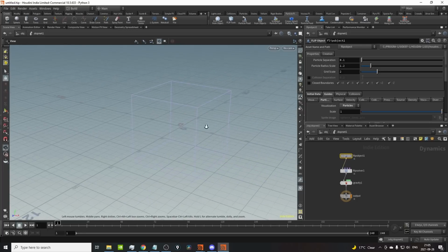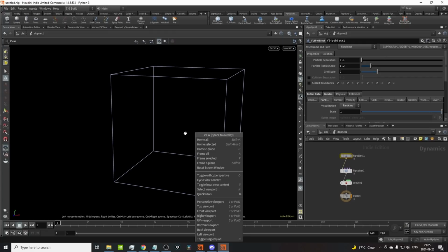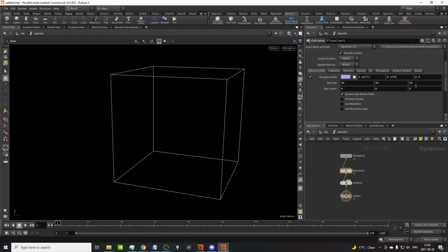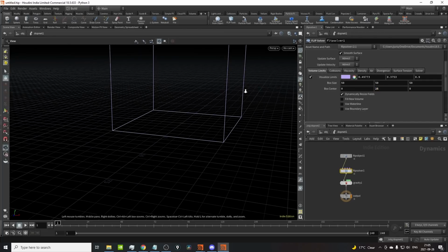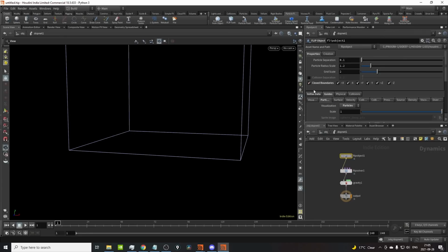By default, if we do everything by hand like I just did, let's change this to dark, we end up with a pretty big bounding box under the volume limits. It's 50 by 50 by 50. We don't really care, that's fine, but what I want to do right now is drop some high viscosity stuff onto the ground, and doing a ground collider is unnecessarily expensive, so instead I'm just going to move this box up so that it lines up perfectly with 0 at the grid. It's just y divided by 2, and now we can go onto our flip object and close the boundaries, which will now give us some collision on them, right?